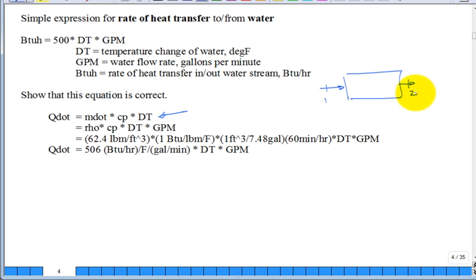You can either think about it being heated or cooled, either one. Whatever that Q dot is, if it's a delta T increase, it was being heated. If it's a delta T decrease, it was being cooled. It's always liquid water. So the change in the enthalpy from H2 minus H1 is approximated C sub P (T2 minus T1). True? Just write the first law for a system.